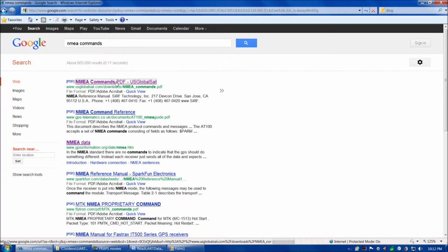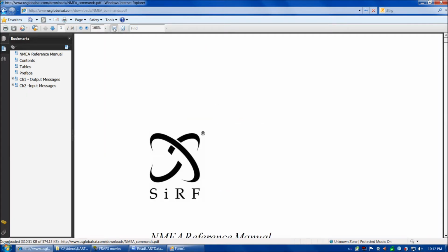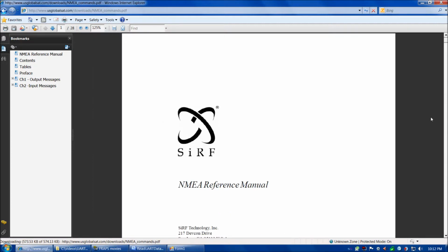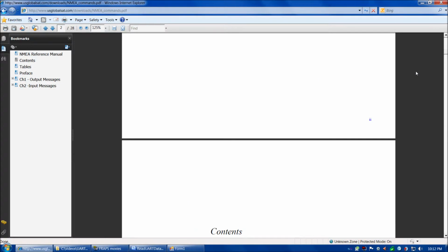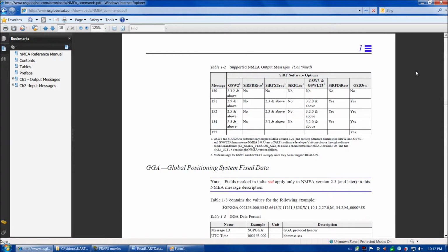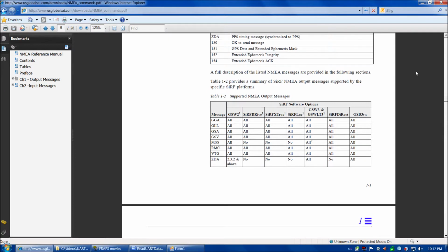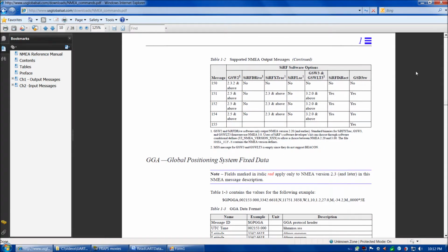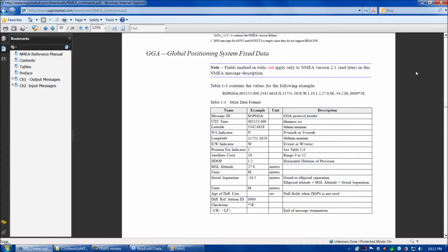You'll pretty quickly get to this document here. And if you use a different GPS receiver, that's okay, because these NMEA sentences are pretty much an industry standard, so whichever GPS unit you're using will probably use the same format. Eventually, if we work our way down, here's a list of all the different possible formats, but the one especially of interest to us is the sentences that start $GP and then GGA. This is going to have the general purpose GPS data we're looking for. So it's going to start $GPGGA, then this field here is going to be the UTC time, universal time.